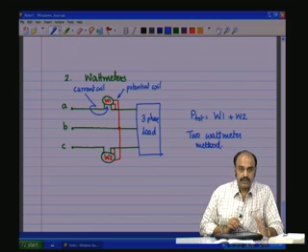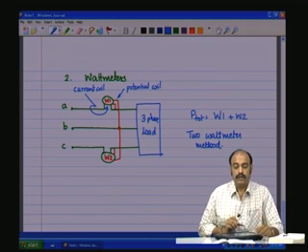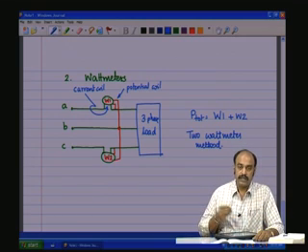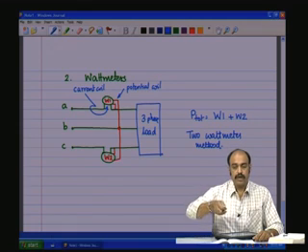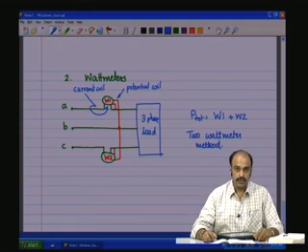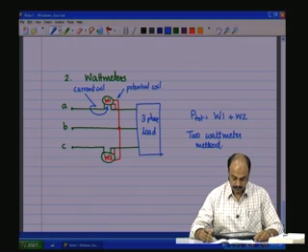So, if there is a center 0 wattmeter, then you can take the readings easily. Otherwise, if it is just a one direction wattmeter, you will have to reverse the direction if it goes negative, when the power factor is pretty low.